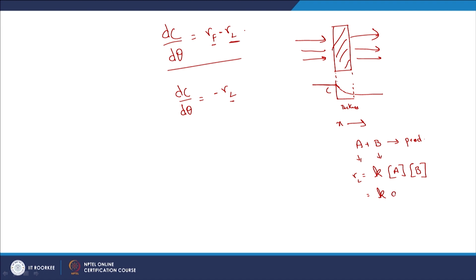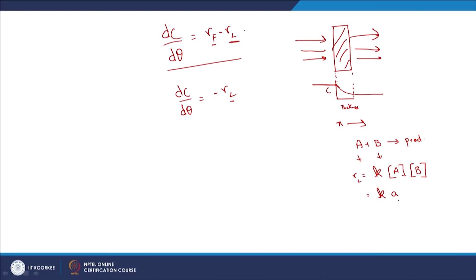We have the surface area per volume of water, because it is 0 valent iron, you have pellets, and the water or the compound comes in contact with these pellets. So, we are concerned about surface area per volume into the concentration of the relevant compound, let us say concentration of B here. And what does this depend upon? Again, as we know, the rate constant times A depends upon the specific surface area and concentration of 0 valent iron, into the concentration of the relevant contaminant or compound, right. So, this is my rate of loss.